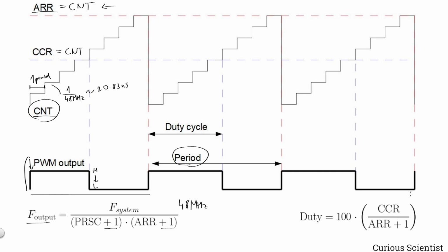And that is nothing else than just the CCR value. So this, which I showed you, determines when the PWM basically changes sign, divided by the auto reload register plus 1. And actually, this is just a non-integer number. If you want to make it an integer, or express it as a percentage value, because this will actually be expressed as a percentage, then you just multiply it by 100. So if this expression becomes 0.5, then of course the whole expression will be 50 percent.